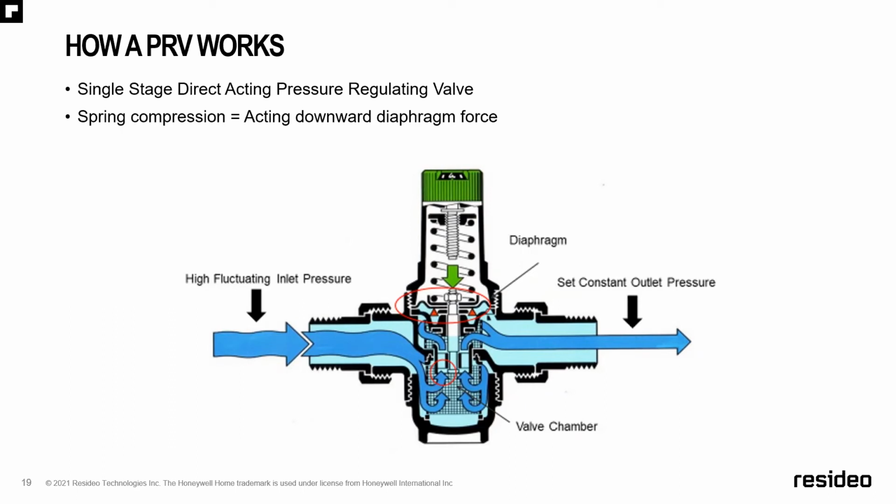If you have big swings in water pressure, it's going to affect not only your tank type water heater, but your tankless water heater for that matter, because tankless water heaters are very, very strict on water flow. If you don't have good consistent water flow on a tankless water heater, you're going to have huge pressure swings at the tap. So this is why pressure reducing valves and having consistent pressure are so important when you're looking at a water heater application.